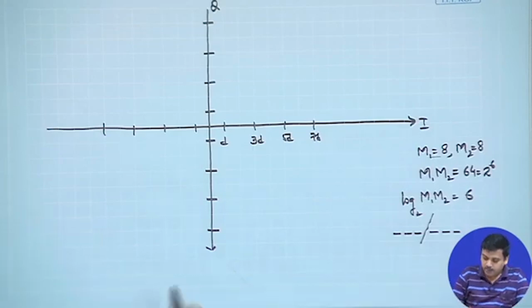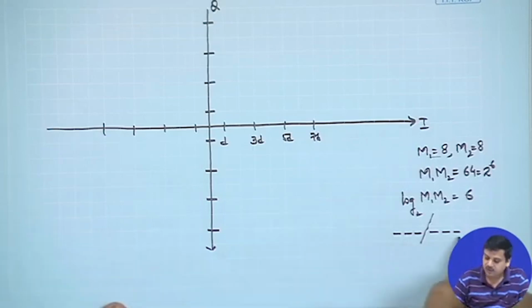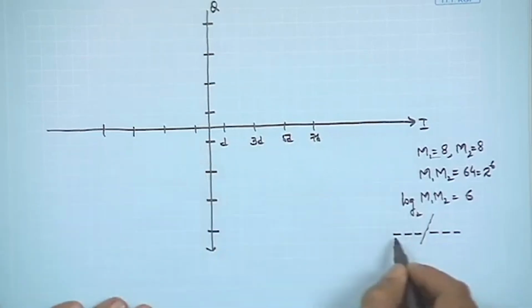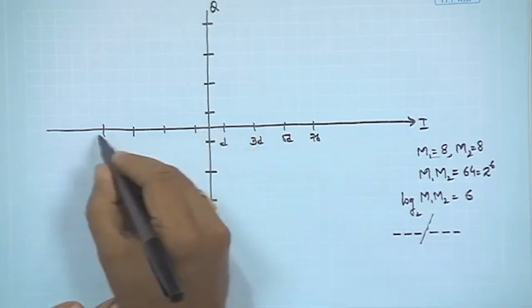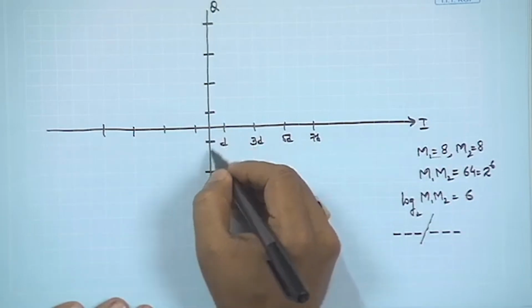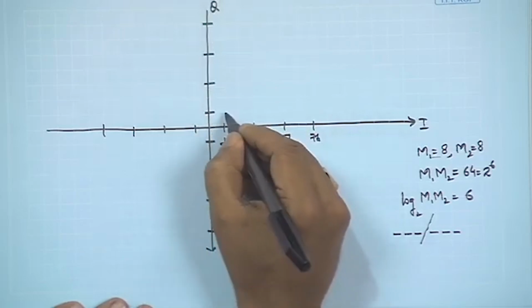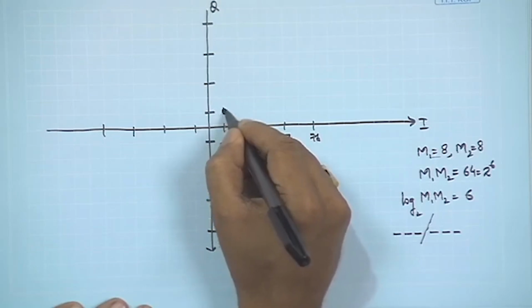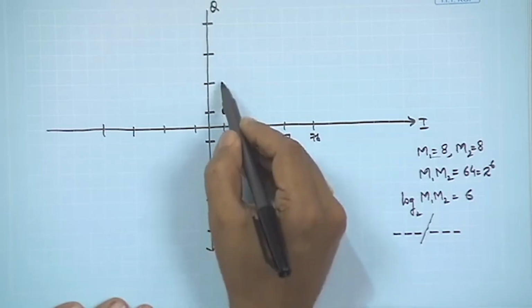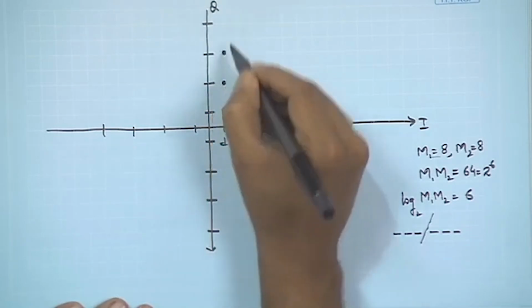Similarly, here also you can think of it as 6 bits in all and there are 64 levels that could be generated, and you could choose the 6 bits to map to any of the 64 levels, or you could split it into 2. So, for example, if we have to select one amplitude on the I axis, suppose we choose it as D, and on the Q axis also we choose it as D. Together, the constellation point would come over here, and if it is D on the I channel and 3D on the Q channel, it will be there, and so on and so forth.